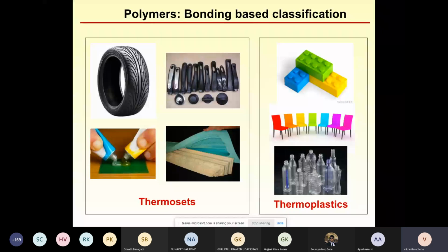Now at this particular loading, if you have some amount of sliding or complete sliding, you can imagine the kind of heat which will be generated. Now, despite the heat and shear stress, you do not want the material to soften or wear out. Okay, so you need materials in such kind of applications to not degrade with elevated temperatures.